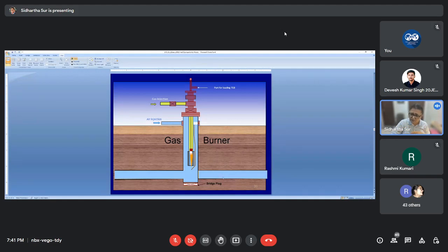400 degrees C to 800 degrees C. So this burner raises the wellbore temperature to around 400 degrees C. We cannot go more than 400 to protect the casing of the well, but it is good enough. When air comes in contact at 400 degrees C, immediately a front is created at the wellbore and gets propagated outside. Okay, so this is artificial ignition.